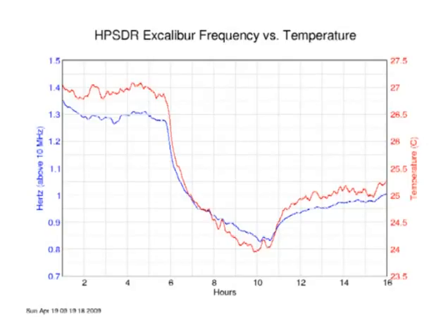We did some other tests that actually showed frequency versus temperature. We subjected it to about a 50 C range and tracked all that. It works real well. Short of an oven oscillator, you're not going to find anything significantly better, and it's stable enough that at HF you'll never see whatever drift it has, in the HF frequency range. Yeah, we have an oven anyway with LPU, right? Just no control loop. So this is another project for one of you guys. Build an oven controller using LPU as a heat source, right?